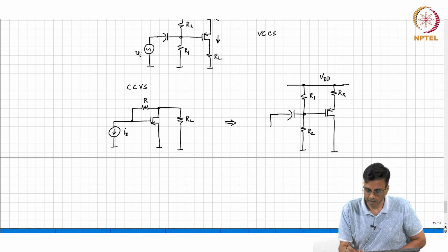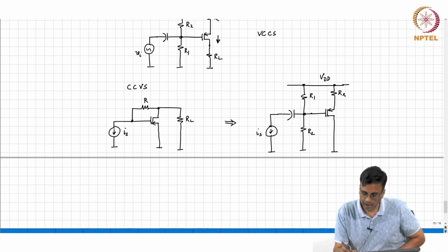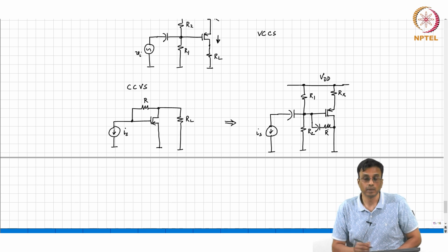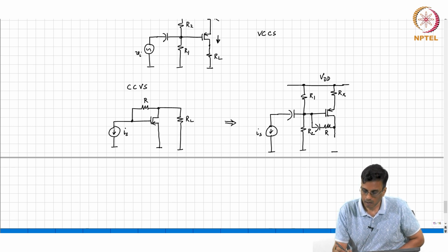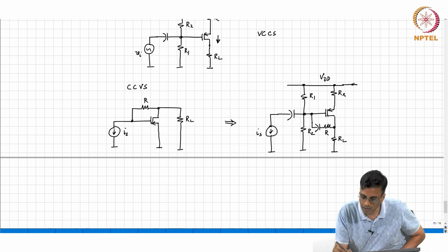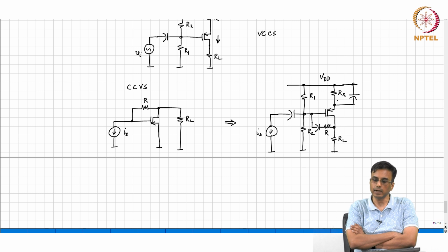That is the input source. Okay. Connect gate and drain. Yeah, use a large capacitance in series if you don't want to disturb the operating point. Okay. What else? Okay. That is RL. Okay. What else? We need the source to be incrementally grounded. We connect a capacitor, right?